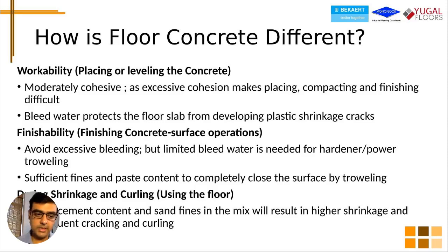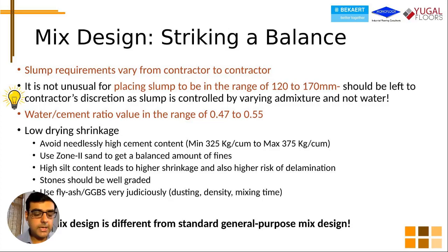I'll go back to the pictures again, and I hope these points will become obvious when we take a relook. Finally, as a user of the floor, you want to have minimal shrinkage and curling in the slab. And as a floor constructor, I can ensure that by limiting my cement content and limiting my sand fines, because higher cement and higher fines in the sand will result in higher shrinkage and curling and consequently cracking.